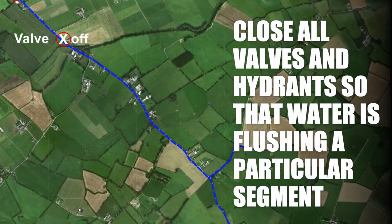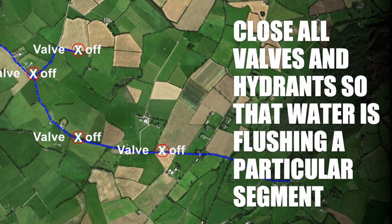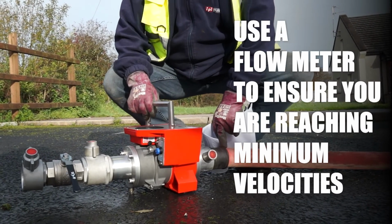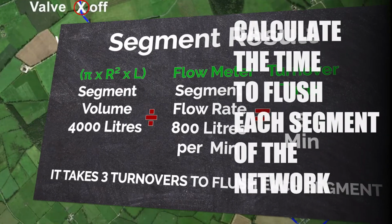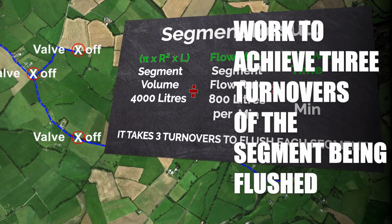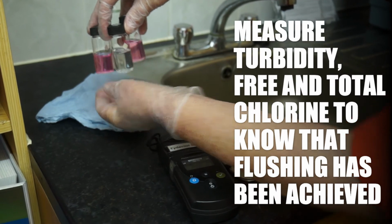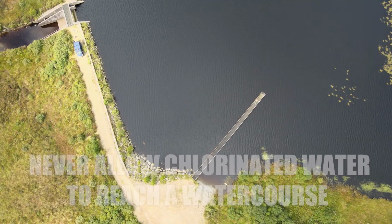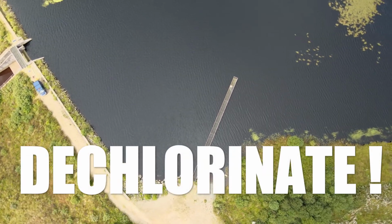Close all valves and hydrants so that all of the water is directed at flushing a particular segment of the network. Use a flow meter to ensure you are reaching minimum velocities. Calculate the time to flush each segment of the network. Work to achieve 3 turnovers of the segment being flushed. Measure turbidity and free and total chlorine to know that the flushing has been achieved. Do not allow chlorinated water to reach a watercourse. Dechlorinate.